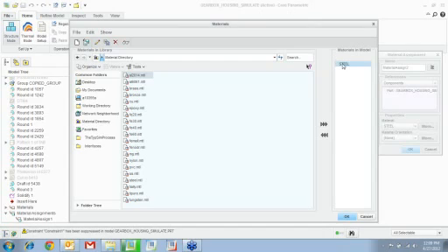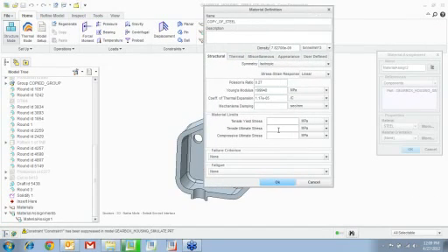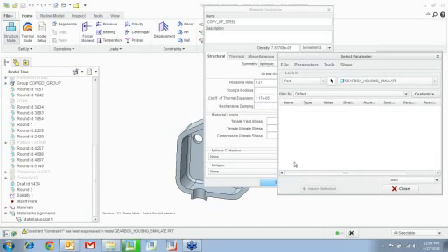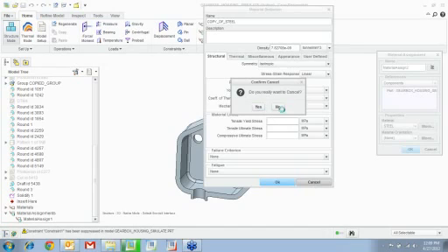What you can also do with respect to materials is you can use the existing one, make a copy of it. Okay, so here I'm going to make a copy of steel. I'm going to double click on that. You see you have all your standard properties, isn't it? What you can also do right here is you can get rid of the Young's modulus, for example. Right click, you can insert a function or you can insert a parameter. So let's say a parameter. We don't have any, so I'm going to go real quick and create one.